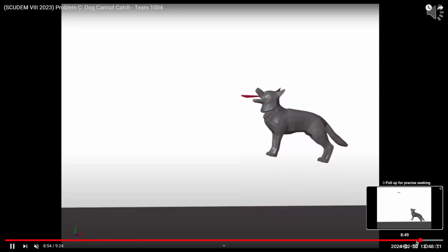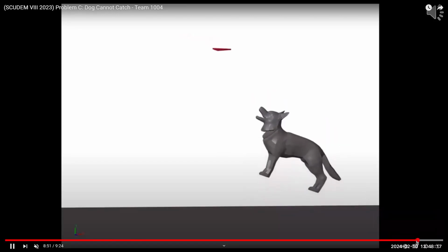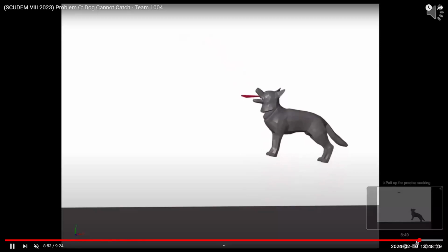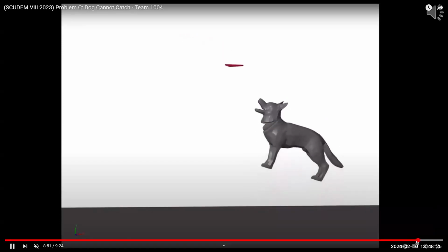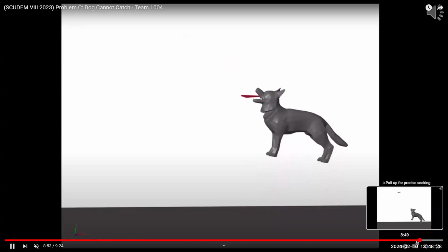And in Simscape, I can take data from this and export it directly to MATLAB where I do calculations. Oftentimes, for instance, if I have a 3D system, I can model a spring and a block, make a vibration between them, and then measure the output. And I can obtain things from that output, such as your natural frequency or your spring constant.